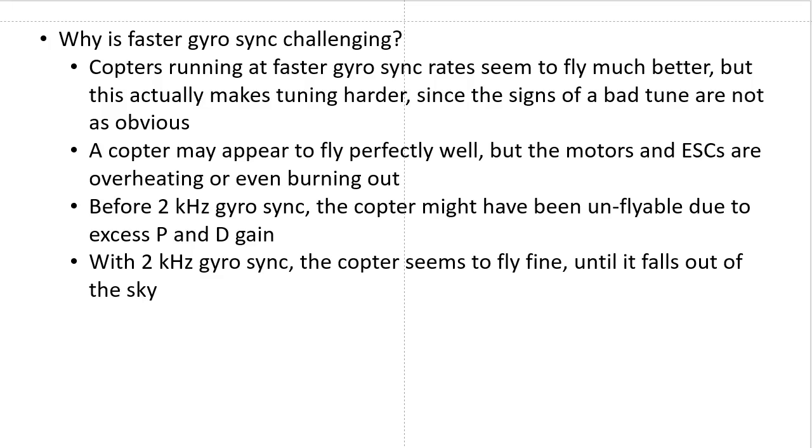I think that at 1 kilohertz, you could still tune line of sight and with your HD cam pretty well, although it got a little challenging if you didn't know what you were doing. And with 2 kilohertz and above, from what I'm hearing from people, it seems like with line of sight tuning, you could probably make it fly good, but you won't know what's going on underneath. You won't know if you've got huge P-term or D-term oscillations unless you've got Blackbox. So I really feel like Blackbox is going to be a critical part of tuning going forward.